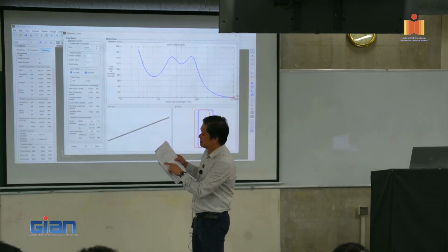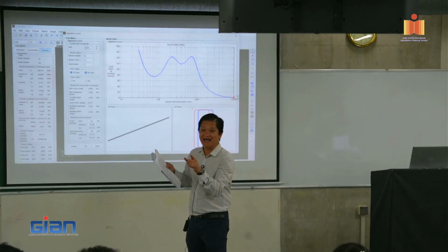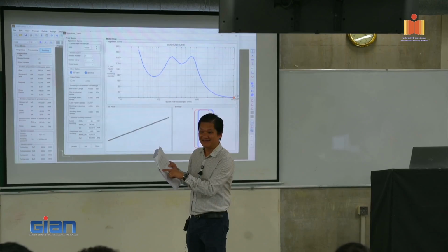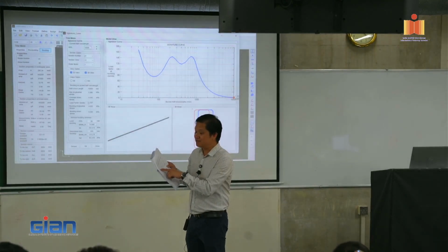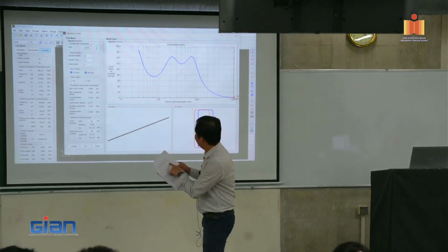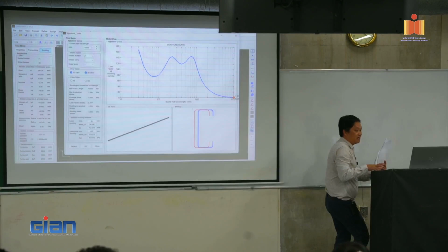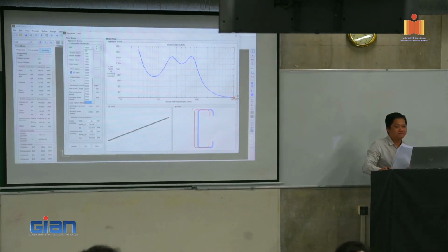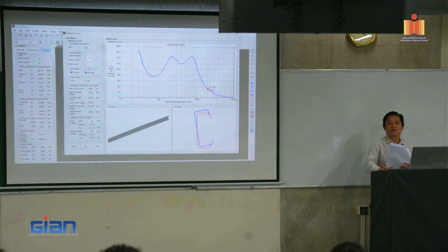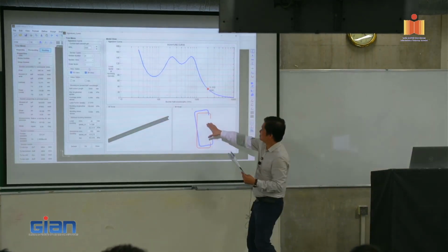So in those equations, it depends on length L. So when L is very small, it means that you've got a short column, for example, you design for 2 meters maybe. So you can see that it buckles sideways and twists.